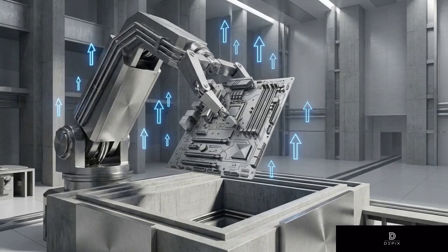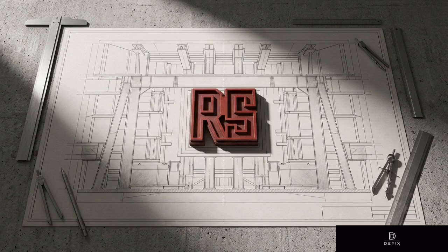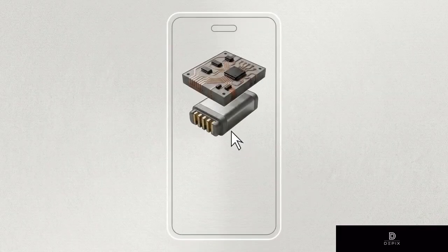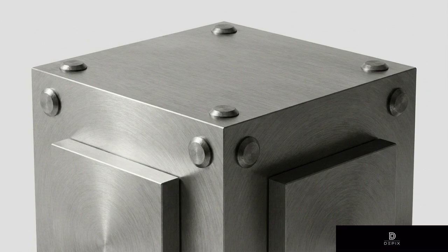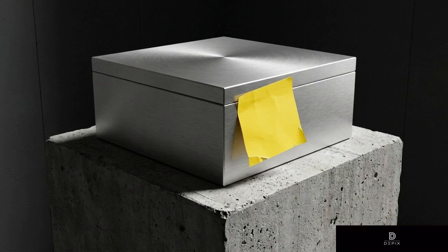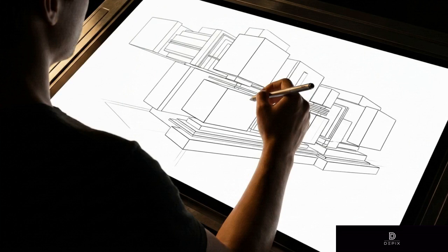Device maintenance is simply the factory assembly process run in reverse. The exact sequence of that process is permanently locked in place the moment a design team finalizes their initial layout. Placing a battery above a motherboard instead of trapping it underneath is a painless choice if made early. Once the design moves forward, it becomes structurally impossible to reverse. Repairability is not a feature you add at the end of a development cycle. It is a shape drawn at the very beginning.